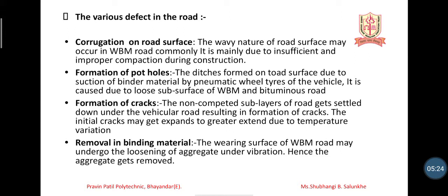The initial crack may expand to a great extent due to temperature variation. You can see why the crack has happened: because of the non-compacted sublayers. If you're not compacting properly, then obviously after some time that part is going to go down, and because of that the crack will be formed.